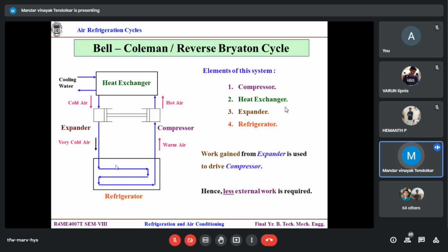And we know that compressor work is the input, the denominator in COP. Refrigeration effect divided by compressor work. So if I could reduce the compressor work, my COP will be increased. Anyways, turbine or whatever expander you are using, that work otherwise would be just a wastage.